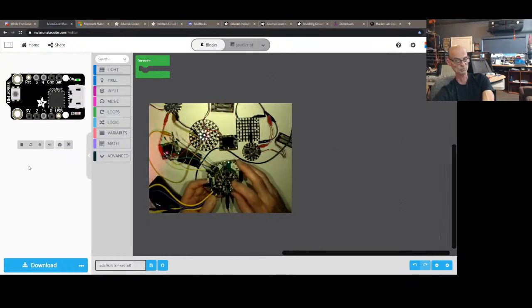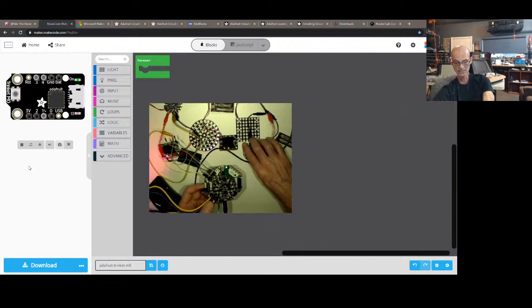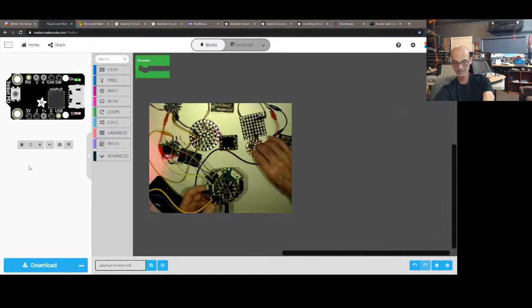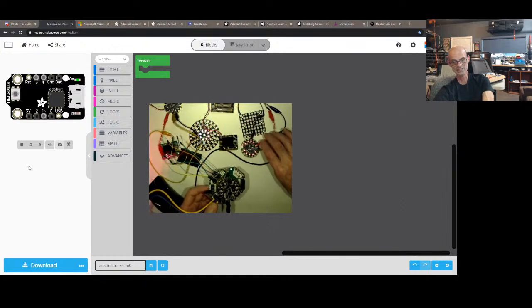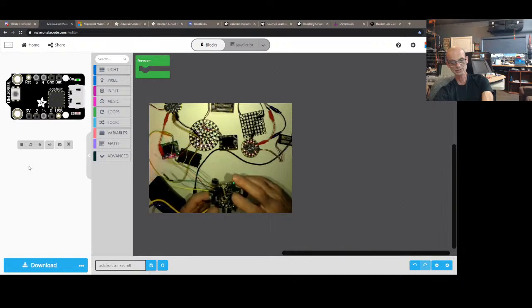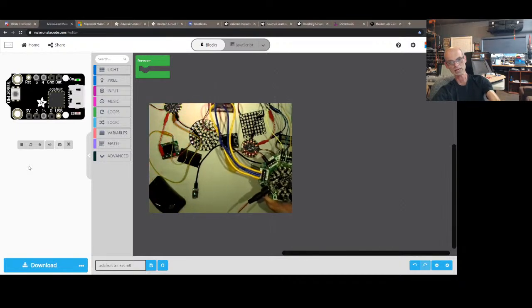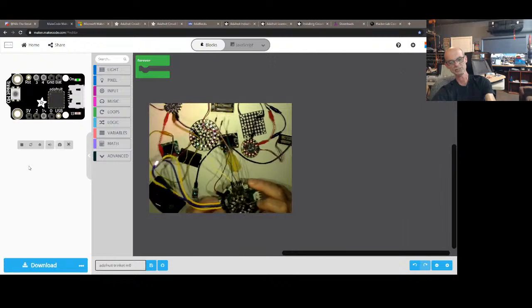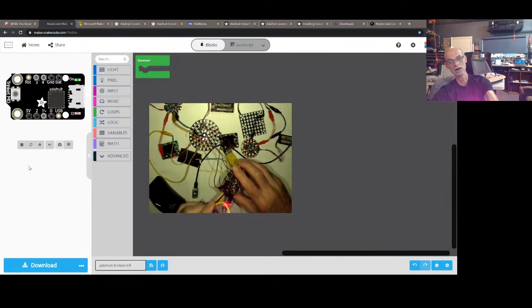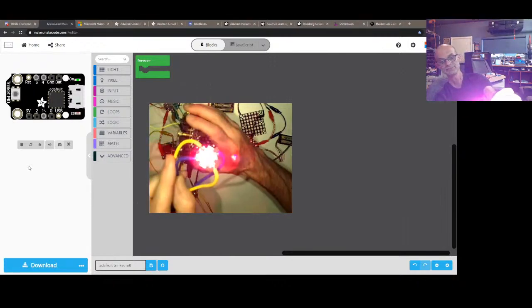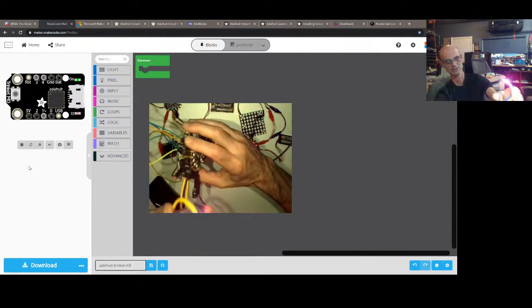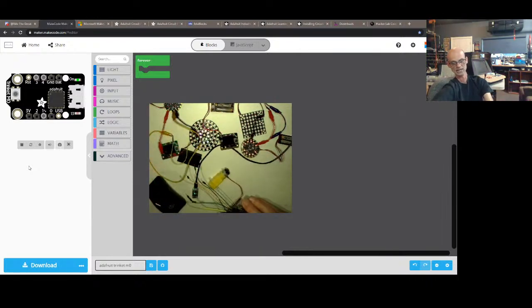The traces aren't super thick on these. When you look at them, they are not intended to carry a lot of electricity. So this daughter board here allows you to see, I have a separate power supply plugged into it, and allows you to do things like drive a high power LED. This is going to be like a 3 to 8 watt range.